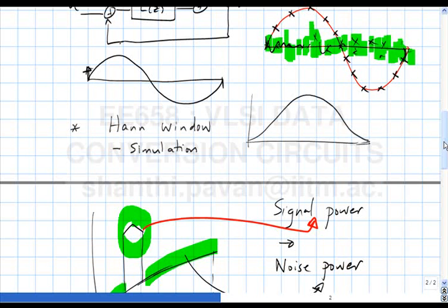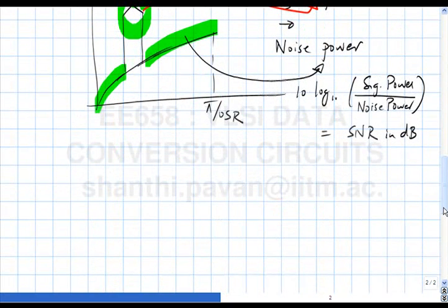Okay, so what else? Yeah, before I wind up in a couple of minutes, as you can see, this quantization noise appears random, even though technically it isn't. It's very much deterministic, but it appears random, and that randomness increases as the number of levels in the quantizer and the order increase.